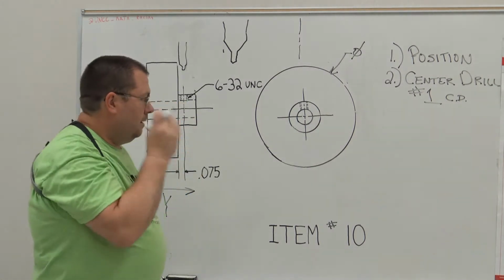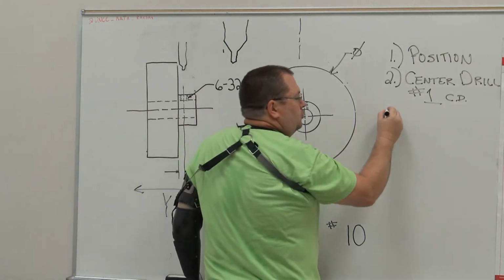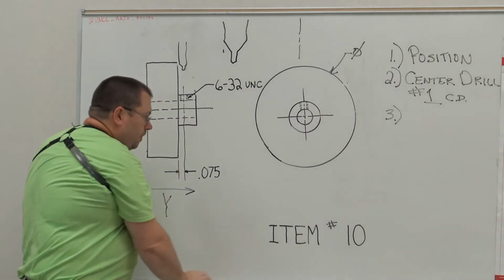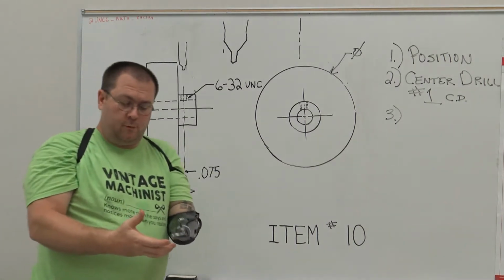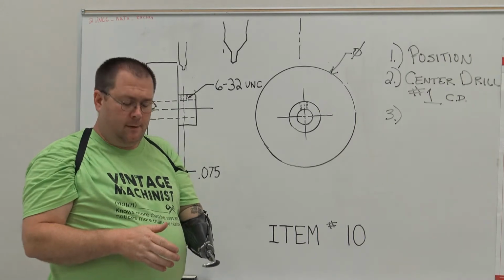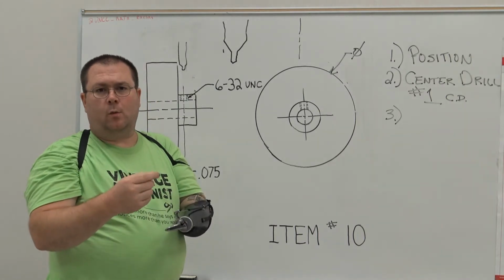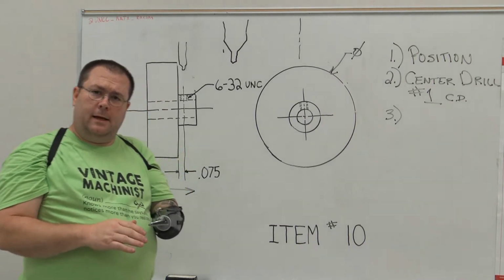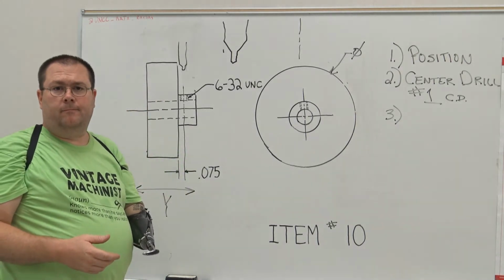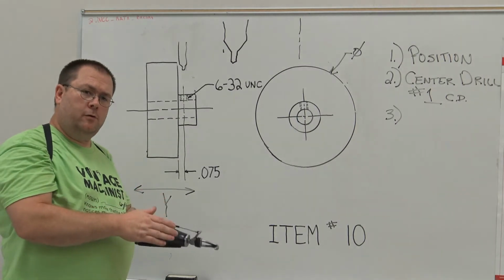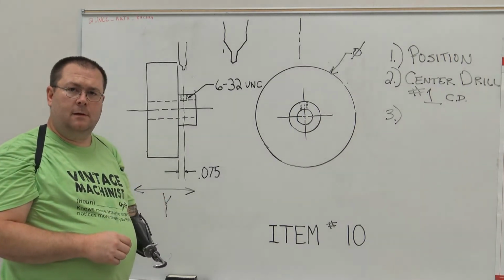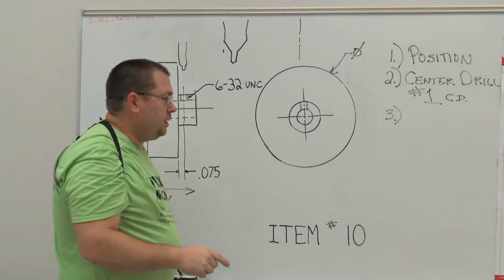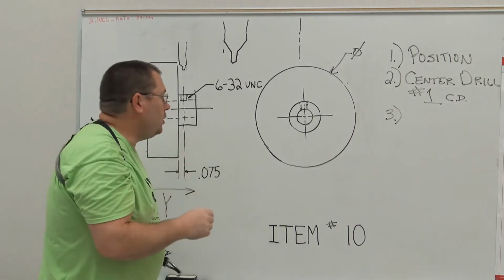Okay? Now when we talked about drilling, we said, I had a really big drill bit that was relieved, and it was ground down so that the web of the drill bit is ground down to a point. That's called a split point drill. You should have that in your notes if you've watched this series. It's a split point drill. Well, what a split point drill does in production, we've already been through this, but I'll touch on it again.